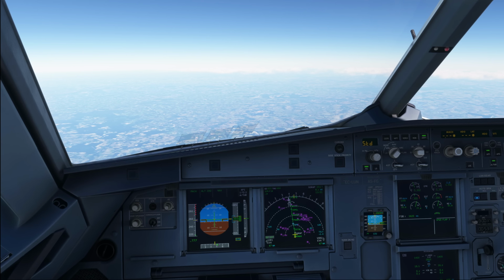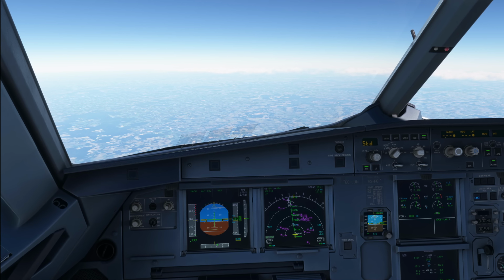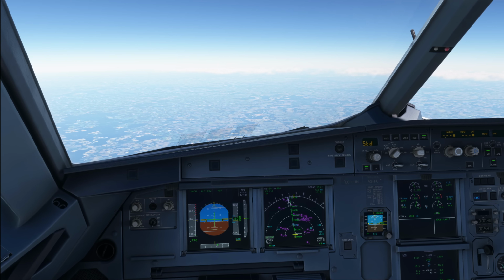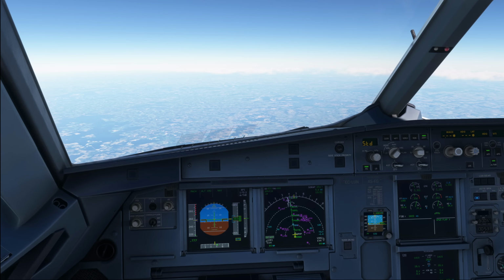Going on then to the cockpit preparation. On the INIT page, the flight crew should respectively check that the cost index is consistent with a computerized flight plan, as the CI is the ratio of time cost versus fuel cost. The purpose of the CI is not to reduce fuel consumption, but to reduce overall operating cost. Also make sure that the tropopause value is correct in order to ensure the accuracy of FMS prediction.